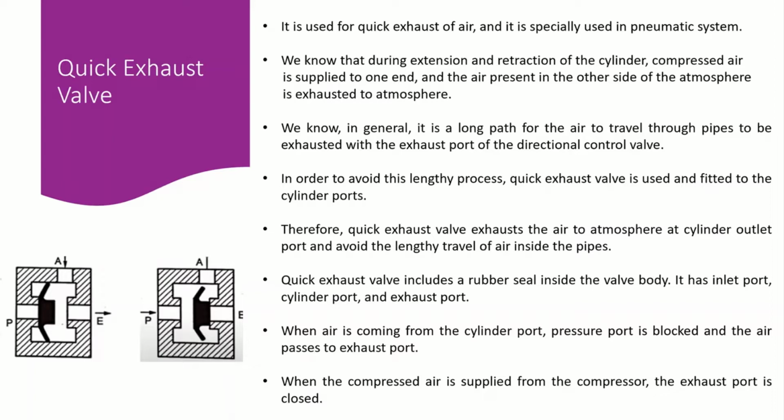One important thing is that during the extension and retraction of the cylinder, compressed air is supplied to one end, and the air present on the other side is exhausted to the atmosphere.